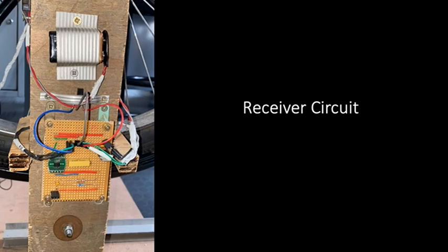The receiver detects the light being transmitted via a transimpedance amplifier. This form of circuitry consists of a photodiode and an op-amp that converts a received current signal into a voltage signal that can be sampled and processed digitally. The signal is further conditioned to mitigate any noise from ambient light that may distort the received signal. The final conditioned signal is sampled via a Tektronix 5 series oscilloscope, which was able to sample the signal at 625 megasamples per second. The recorded signal then can be later analyzed for any shifts in frequency.